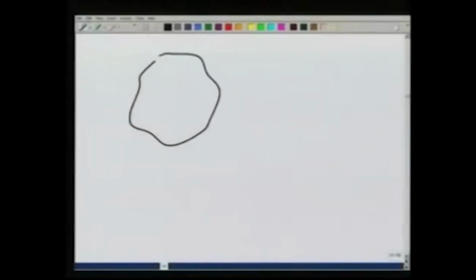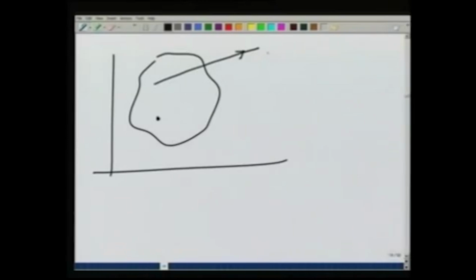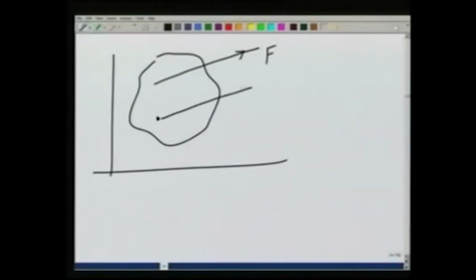How do I understand this? So, let me take a system and let us say it is free to rotate about this point, it is held here, and I apply a force like this F. Let me now add a 0 force, but a very carefully chosen 0 force onto this rod. I will apply a force in this direction and in this direction of the same amount as F, which is a 0 force, F in one direction and equal and opposite force at the same point.